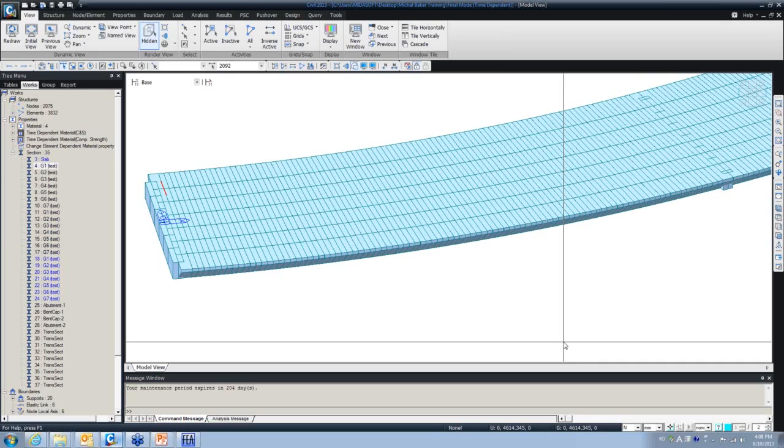So you can use any section, but normally what we do is use the same thickness as the top slab. So for this model, we can use the top flange elements. The transfer elements technically ensure that the girders are working together, and also ensure that there is the torsional stiffness or the lateral stiffness in that direction.